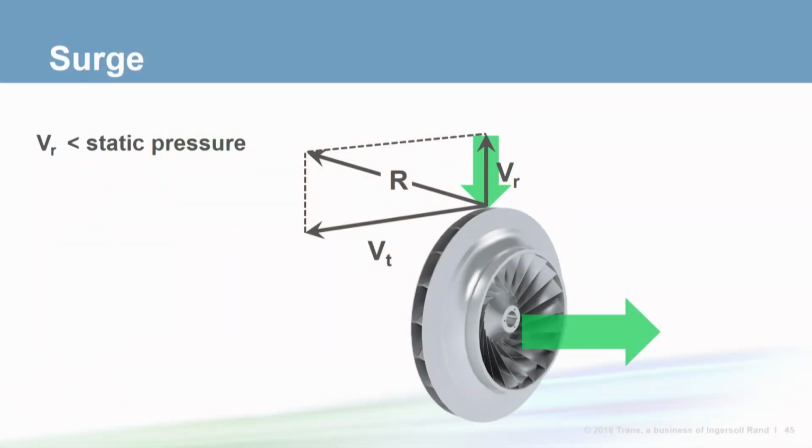Chillers also have a high pressure cutout set for the condenser so that the same situation of the chiller shutting down can occur on the condenser side if the flow rates are too low. For a centrifugal chiller that is dynamic compression, you also have the concern of causing the unit to surge. And surge occurs when the amount of lift needed to be generated exceeds the amount of lift the compressor can actually generate. This results in refrigerant flowing backwards, which is called surge. And surge creates unnecessary wear and tear on equipment, and the unit will shut down.